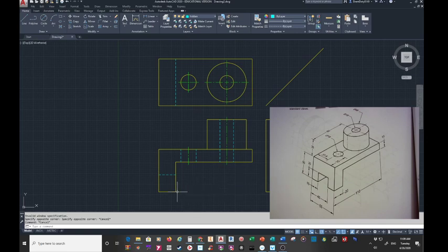And you'll notice that instead of trying to measure this stuff off, where you see it as solid lines, you draw it in there and then project it. I'm going to go to my object layer. I'm just putting these lines in because that's where they go, and you'll notice that this line is solid here. If I drew a left-sided view, that's this corner here. If I looked from over on this side, it would be a hidden line. Well, over here, I see both edges, so they're both solid.